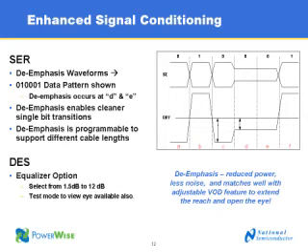The second and third zeros in the sequence, time slots D and E, we've now backed off and we're de-emphasizing the signal. The idea here being we don't want to continue to build up too much charge on the cable. This allows for an easy transition to that final 1 bit that we're sending in time slot F. The overall impact of this is that we get a nice clean eye opening even when we just have single bit transitions following a long sequence of 1s or 0s. In the 905, 906 chipset, the de-emphasis level is programmable, so that allows you to adjust the level of pre-emphasis to be optimized for the cable that you're driving. So just to summarize, this graphic is really showing where that de-emphasis is happening.